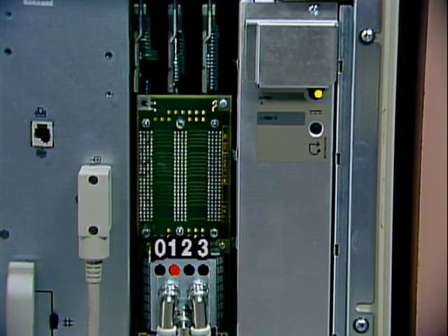Here we have a problem that shows the green LED is off and the red LEDs are off, on, off, and off. The green LED indicates a diagnostic failure because it's off, and the last red LED tells us that the problem is not catastrophic. The failing module is called out by the other three LEDs, with the second LED pointing to the output module as the source of the problem.